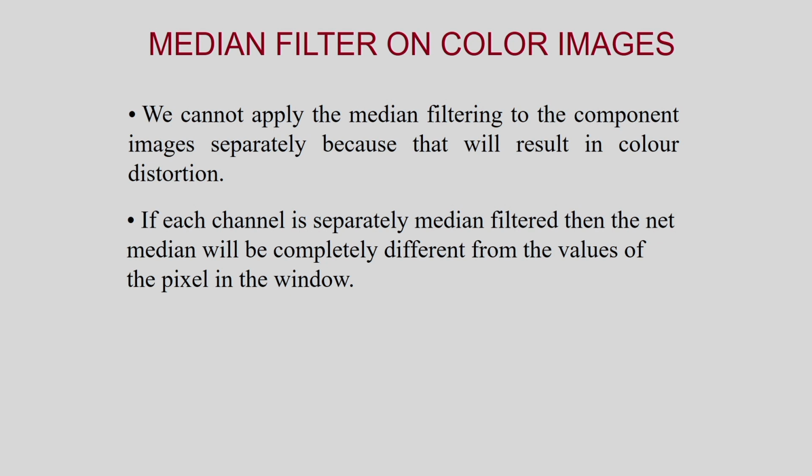After this I will discuss the concept of the median filter. Already I have explained the two techniques of color image processing. One is the marginal processing and another one is the vector processing. And I have explained what is the problem with marginal median. If I determine the marginal median, then the color distortions take place.